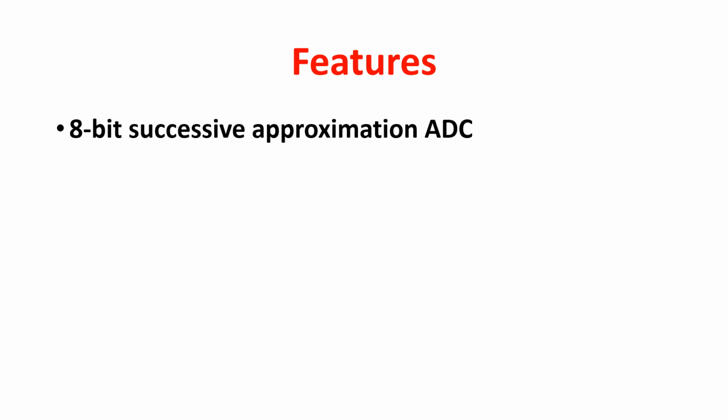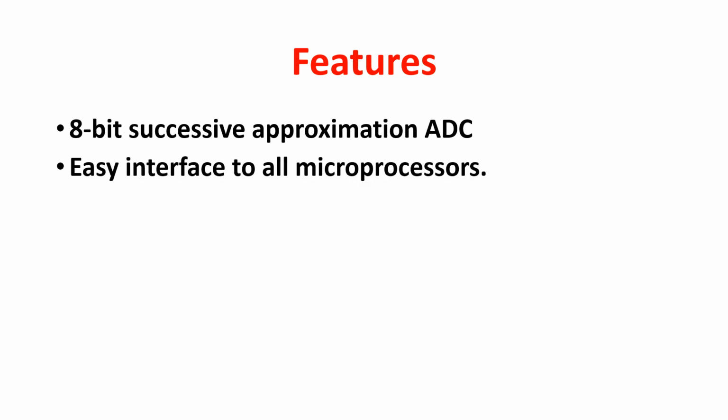Features: 8-bit successive approximation type analog to digital converter. Easy interface to all microprocessors. It operates on a single 5-volt DC or analog span.